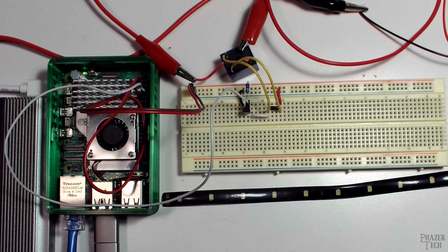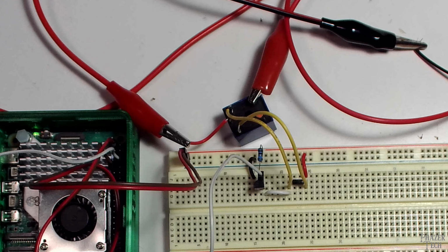Also, something I should mention is that the way the pins are orientated on this particular relay make it incompatible with breadboards. So that's why I've connected it like you see here. I soldered some solid core wires to the coil pins so that I can connect them to the breadboard. I also soldered a red wire to the COM pin, which is connected to the 12-volt power supply. And then I used alligator clips to connect the LED strip to the relay's NO pin.